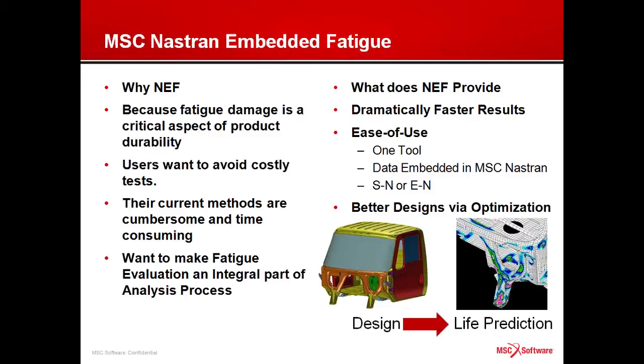So what we have done is we've put the technology that exists in MSC Fatigue, which is based upon Patran, directly into Nastran. The technology that's in Nastran today in this release is complementary to the technology that we have in the Patran product. So what does this capability provide you, the user? It really provides faster solutions. It provides ease of use in having a single tool to utilize stress-number of cycles, S-N diagrams, or strain-number of cycles, E-N diagrams. And finally, it allows you to optimize your designs based upon fatigue information.